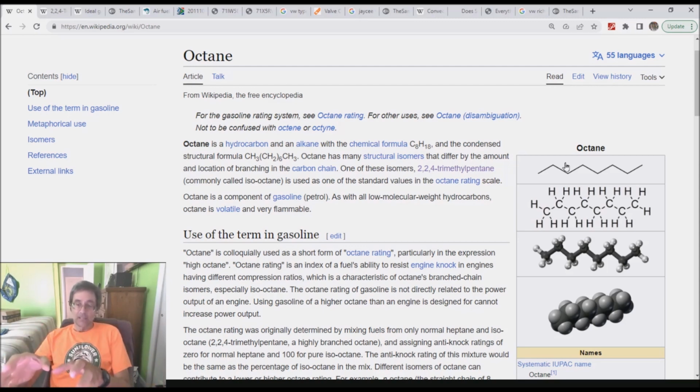The fact that this thing was one particular shape of octane or a different particular shape of octane when it started is transparent to the actual burning process. So the burning process doesn't care whether it was high octane or low octane to begin with. The burning process for both releases the energy of 8 carbons and 8 hydrogens bonding with a bunch of oxygens. It's the same whether it's low octane or high octane. High octane gas will not net you any additional power. So you always run in your car the lowest octane fuel that your car will run properly on. And for me, I happen to run pretty decently on that crappy ethanol 87. That kind of takes care of that one.